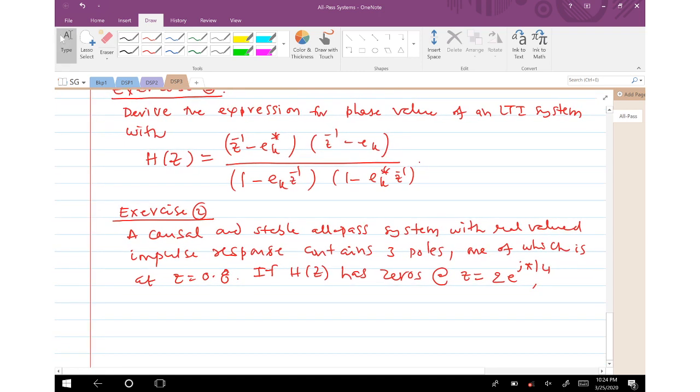With that, what is H of z? That's what you need to figure out, okay. And you write the logic behind how you arrived at that, and write the expression for it, and also draw the pole zero plot for the corresponding one, okay, pole zero plot. And of course you know that anyway ROC is outside the outermost pole, okay.